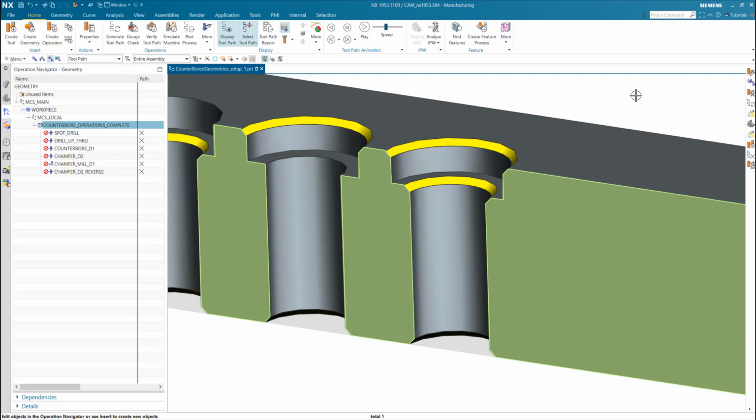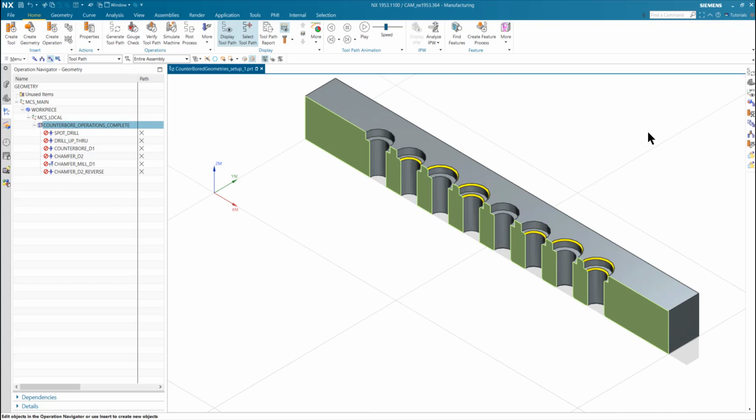Now let us reuse these operations on the full part. The chamfers have a yellow color. That is just to make the visualization more clear and does not play any role. Since there are 3 chamfers that may or may not be modeled, this means we needed 8 features to cover all possibilities. So first we delete the operations that we already had.